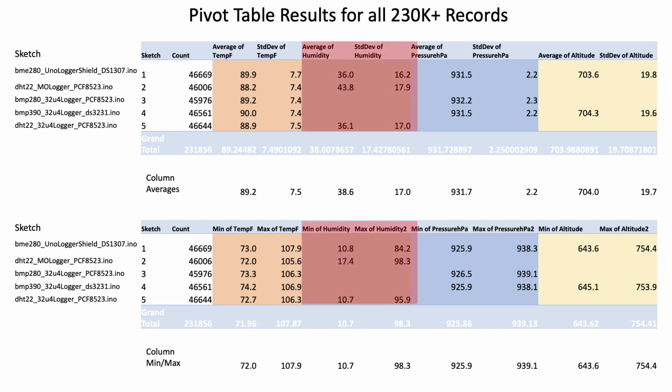Here you can see that the only parameter that actually showed some real difference between all the sensors was specifically humidity. You look at the DHT22, the second data logger that was collecting data. You can see here that my min of humidity was 17.4%, which was different from this DHT22 and this BME280, which actually did match one another, and that showed up in the averages as well.